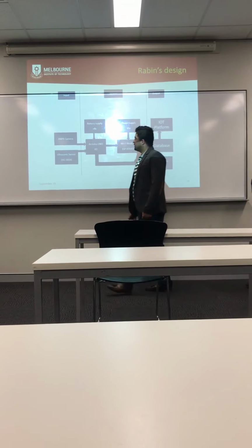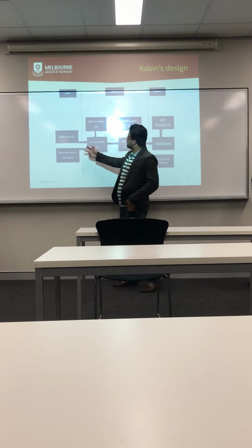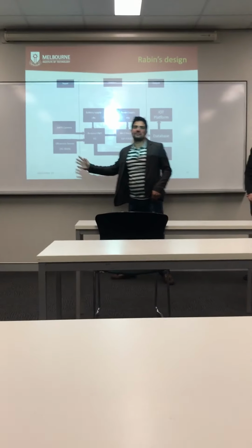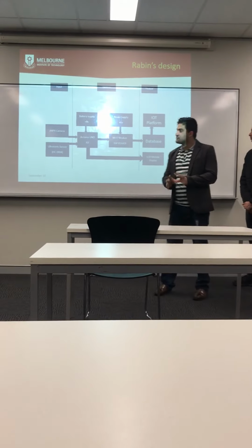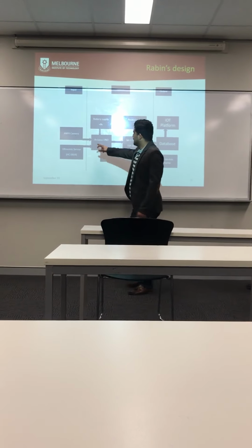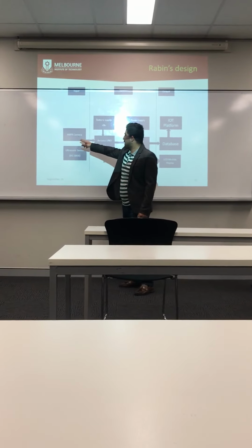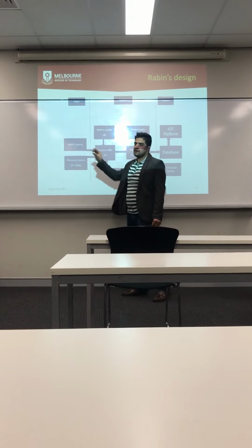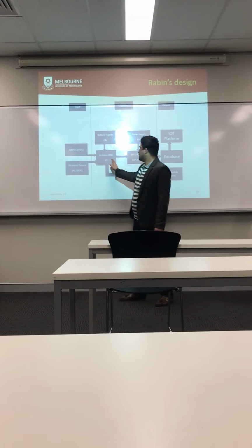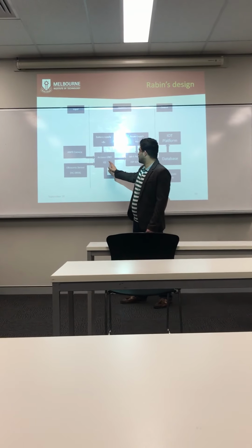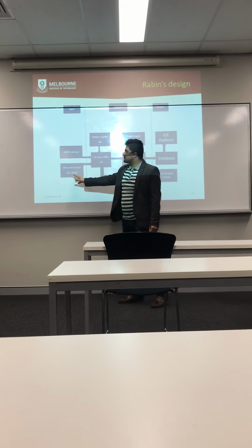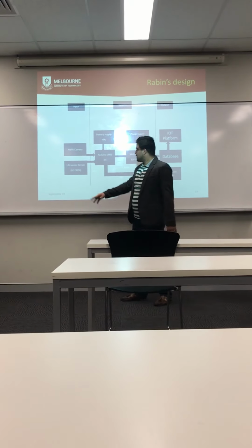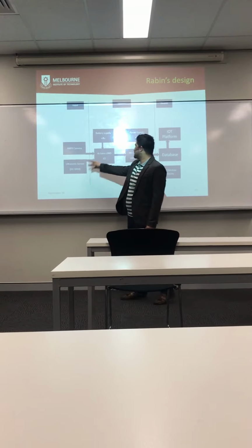In my design there will be an ANPR camera and an ultrasonic sensor. They will reside at the entrance. The ANPR camera captures the image of the number plate and sends it to the Arduino microcontroller, and the ultrasonic sensor detects the distance of a vehicle and sends the data to the Arduino as well.